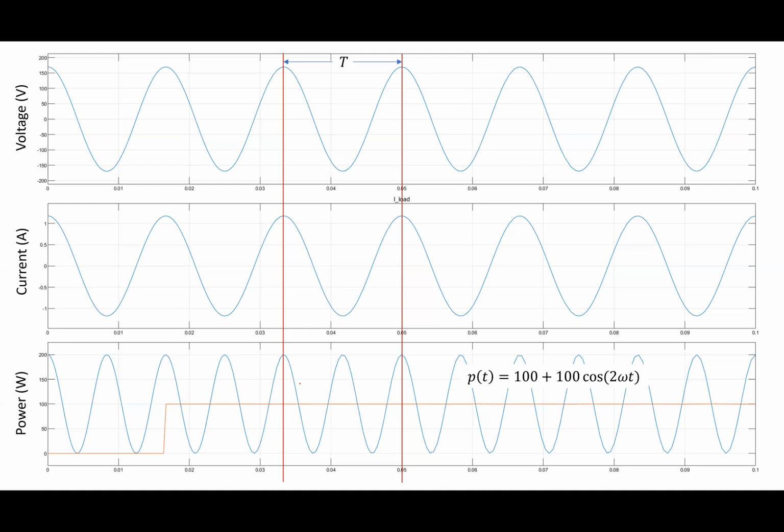Again, the important thing that I want you to understand with this, because one of the questions everybody asks is, why do we do 3-phase? Well, we'll see that when we do 3-phase, P of t doesn't have this fluctuation. Right? P of t is actually just flat. All right. And one of the good things about 3-phase is they don't have that fluctuation. That's good for motors and all sorts of stuff like that. Motors don't like power to fluctuate. You ever seen a single-phase motor?